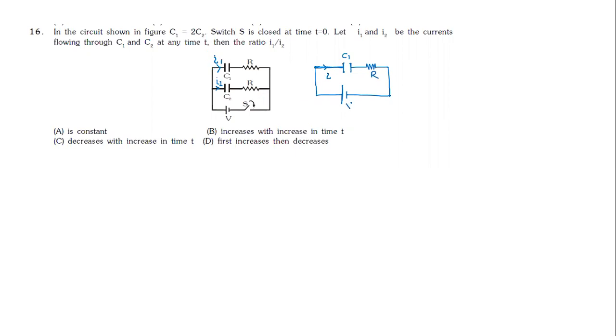Why? Because dq by dt will be equal to I1. When you look at this, what is the voltage available to this combination of capacitor and resistor? It is equal to V. It has got nothing to do with the rest. So for charging of capacitor C1 connected across the battery with no resistance here, these two circuits are identical. So this I will be identical to this one.